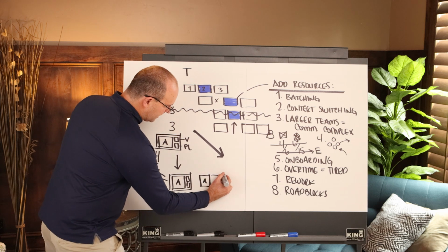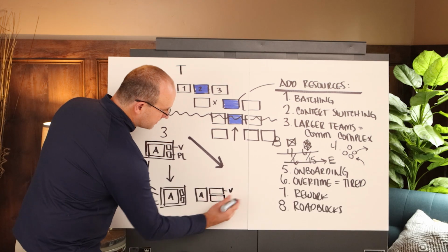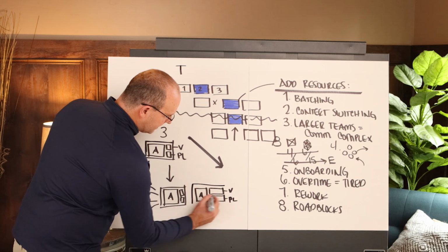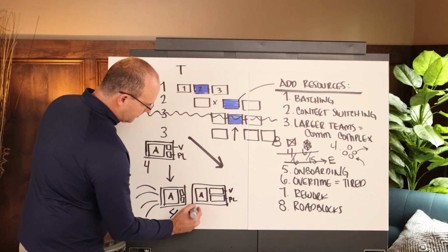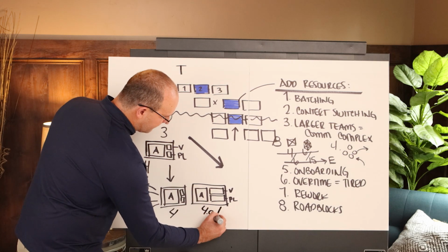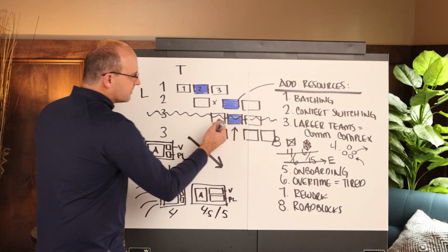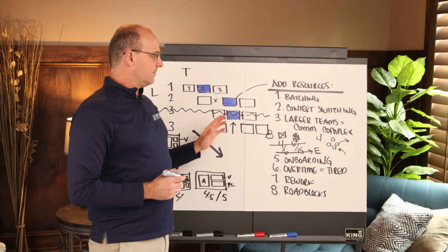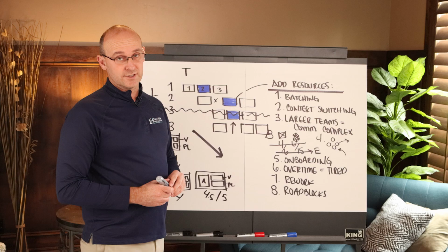What people don't understand is that your variation and your productivity loss, which comes from here, so I'll just write this as PL, gives you a net loss, and your overall time, instead of being 4, could end up being, even though the activity time is shorter, 4.5 or 5 days. This is called the Bungee effect. Instead of pulling it back, it'll bungee out, it'll spring out on you. And so this is a production principle that we have to know, especially when it comes to making sure that our construction projects work well.